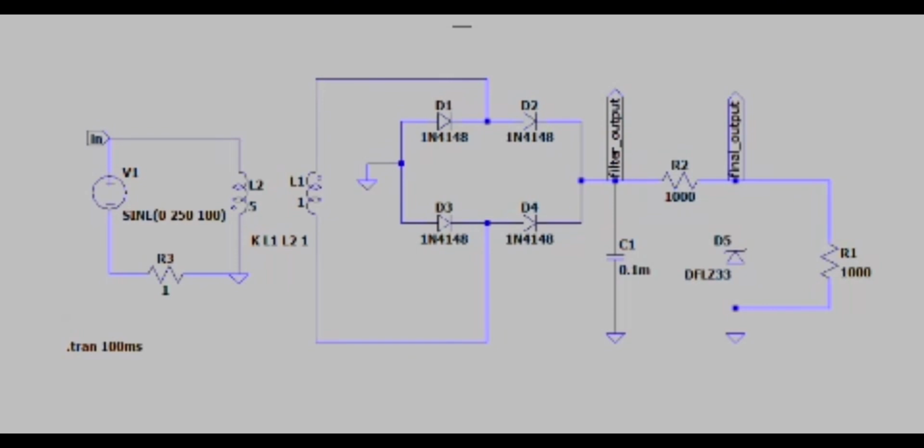The zener diode acts as the voltage regulator. It works in the reverse breakdown region to maintain a constant voltage across the terminal during onset. The zener diode is arranged parallel to the load resistance, which produces the output voltage. The combination of parallel zener diode and load resistance is arranged in series with a resistor, which is used to limit the zener current to avoid the zener diode breaking when the zener current exceeds the maximum current.